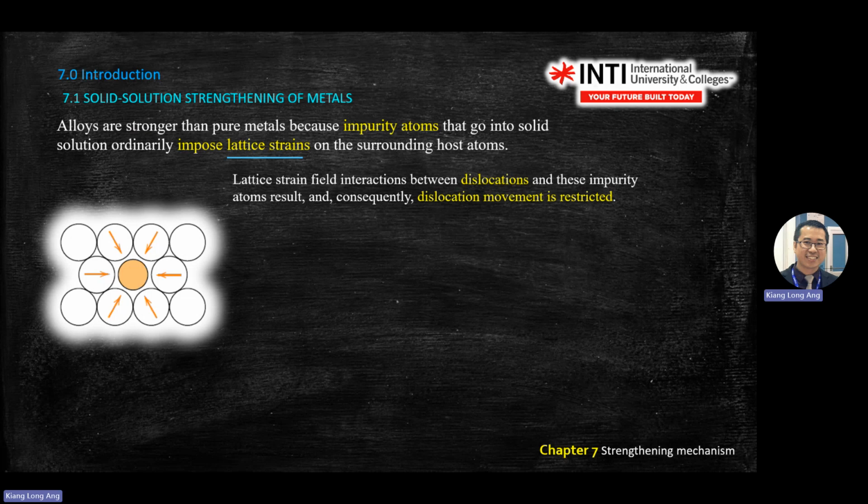Okay, so strain you have two. One is lateral direction, one is a longitudinal direction. You combine these two, you get a ratio. You get Poisson ratio. Okay, so here, about lattice strain. Lattice strain is a deformation of the shape of the cubic, the crystal structure. These are the explanation why, when you add a certain material, what happened to the metals.